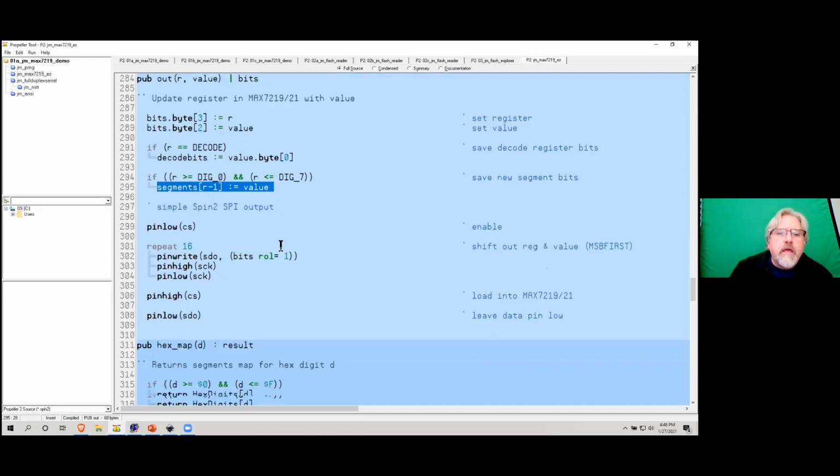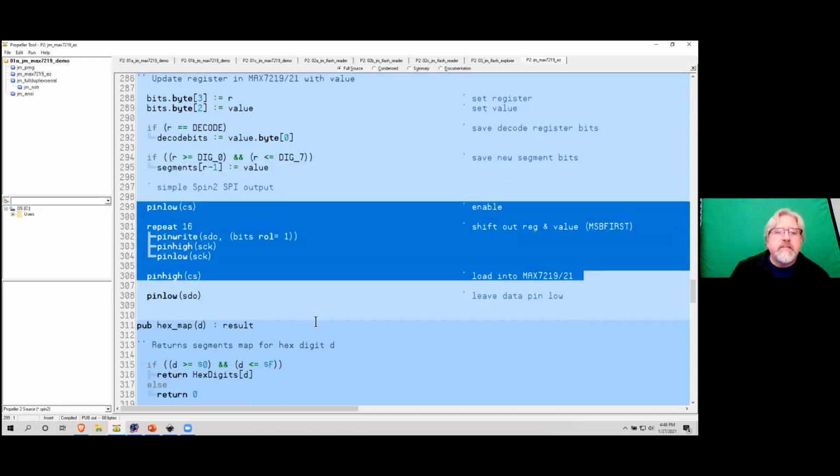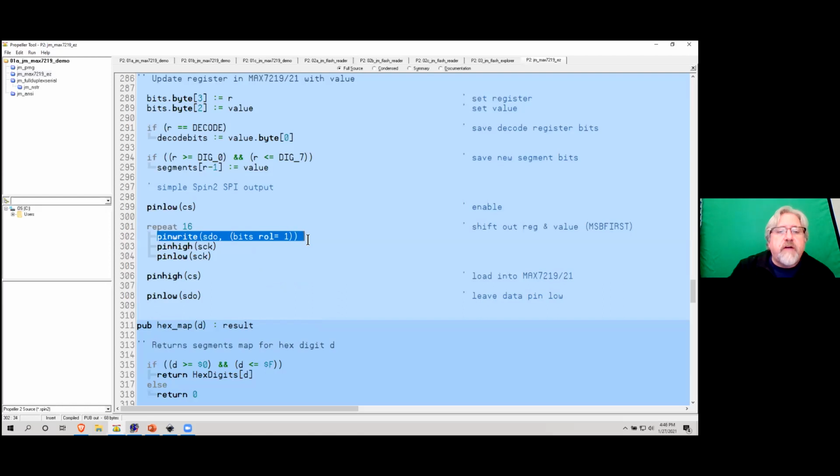Here is the SPI code, believe it or not, this tiny little loop. So you saw in the SPI transactions, remember we start by taking the chip select low. And then in this case, since it's mode 0, the device that is writing to the bus puts the bit out there first.